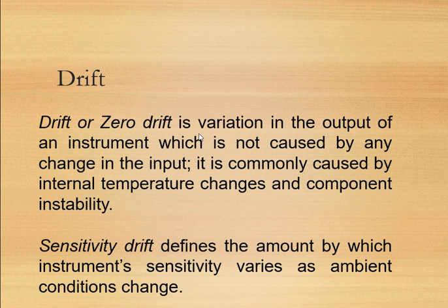So this is zero drift, a variation in the output of an instrument which is not caused by any change in input. That is very important. It means that, yes, of course there is a linear change, but the drift is not caused by this linear change. It is due to some internal temperature and component instability.